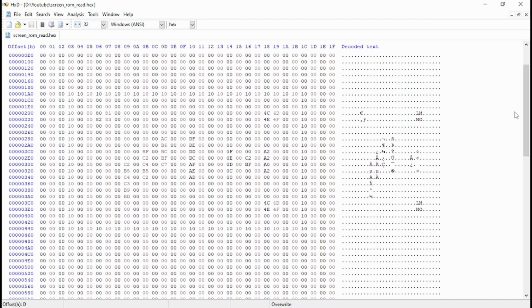So the address of 1A0 in the hex file will be seen as F9A0 in the ROM when we read it. And so in our program, that is reading info from location FB00, that is looking in our hex file at address 0300. And so it will read the whole line from 0300 to 031F.